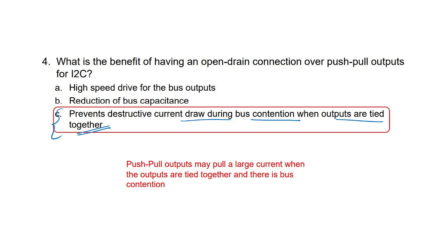So if you are going for push pull output, it may pull a large current when outputs are tied together and there is a bus contention. Okay, this is about today's session.